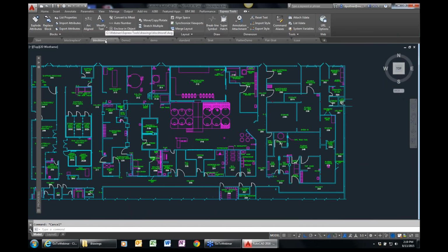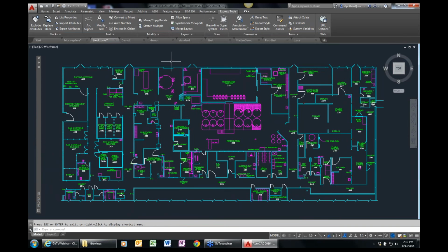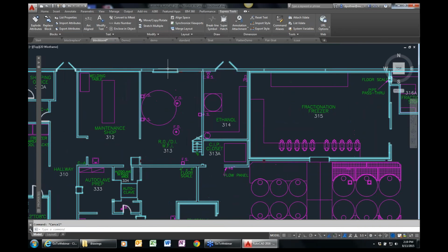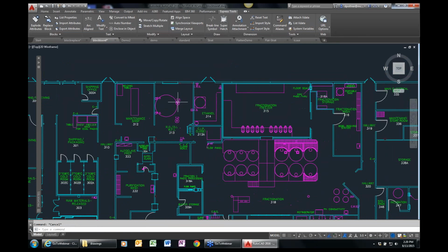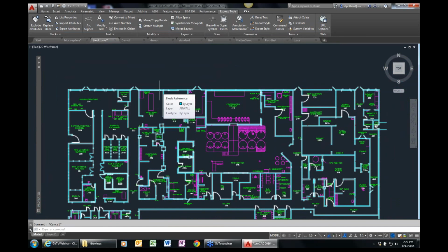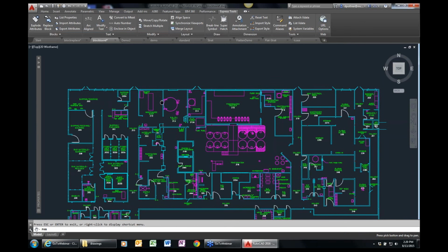So I've got another drawing here, and in this case I'm going to show you a tool that will allow you to convert a block. In this case, this floor plan is actually a block that's inserted in my drawing. Maybe this drawing started out with this being an XREF, and the block got bound by somebody, or maybe you have a different version of it. If you didn't have this, I could always W block this out into an extra file. I already have a file here that I want to use.